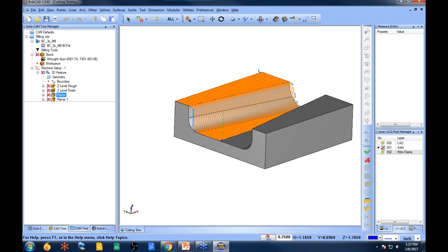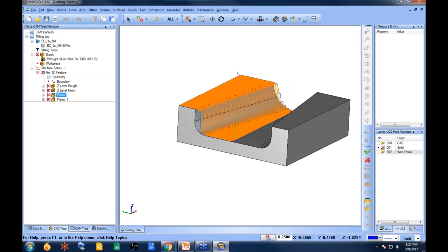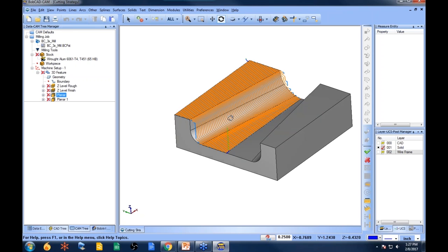Now, what you select plays a huge role in what's being generated. To control the toolpath, to control where it's going to go, it's going to be a combination of what you've selected and what some of your settings are, okay? What you selected to drive the toolpath along, what boundaries you've used to contain the toolpath, your top and bottom of job setting, additional surfaces that you may apply to it. So what do I mean by that?